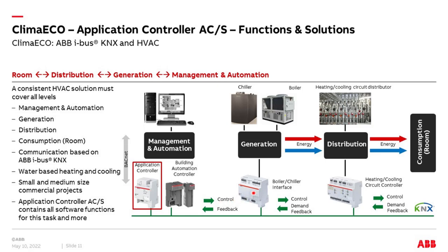With the components themselves, they can interact with each other. You see, everything is connected via the twisted pair KNX cable to each other. You have, of course, also connection, but not the total functionality, which is only possible with a central component here. And a further feature you see already here, it's not only a superior device, but also an interface for BACnet integration. So the very important BACnet protocol, we talked about this already a bit, is also here integrated as an interface.